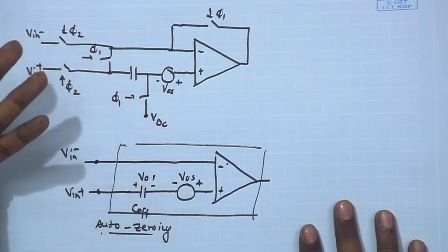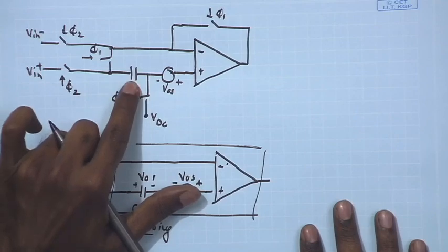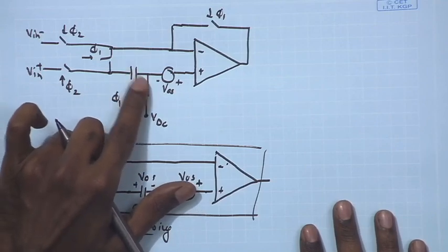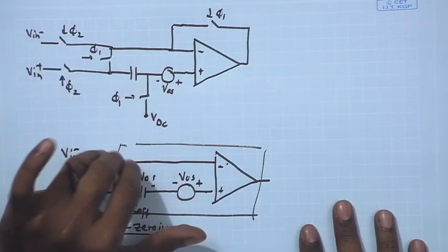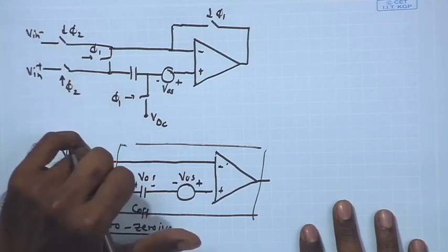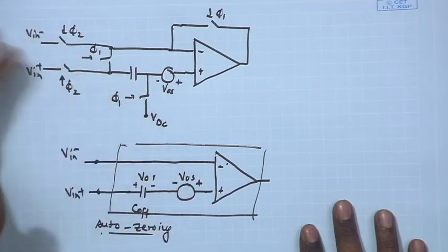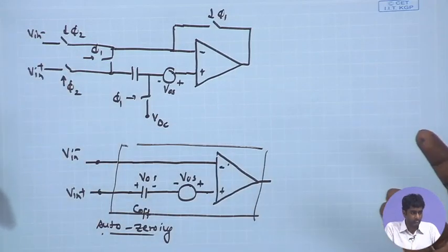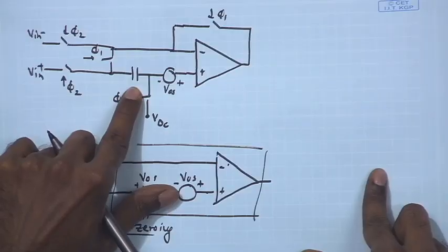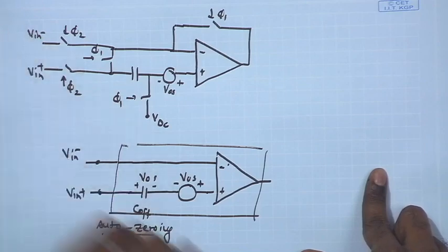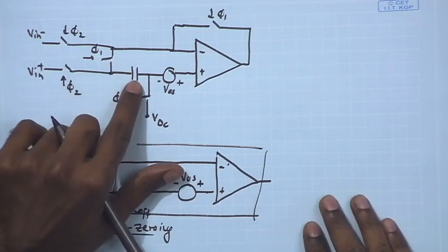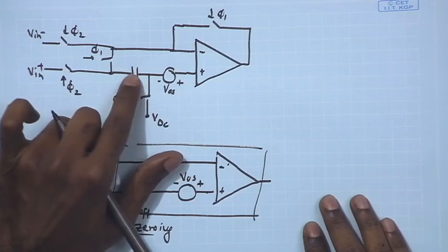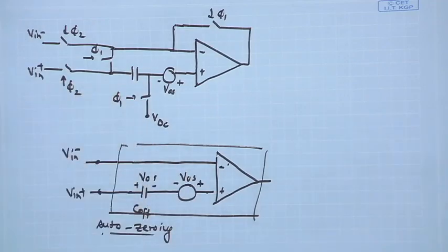So that of course relates to the size of the capacitor. If the capacitor size is large, you can keep the stored charge over here for a long time without it getting destroyed by leakage. In that case, you can refresh it very less often. For example, for the entire conversion cycle, you can do it just once, before the ramping starts. If the capacitor size chosen is small, then you will need to refresh it frequently. So, of course, there is a trade off. If you want to save area and make this capacitor small, you will have to go for very frequent updates.